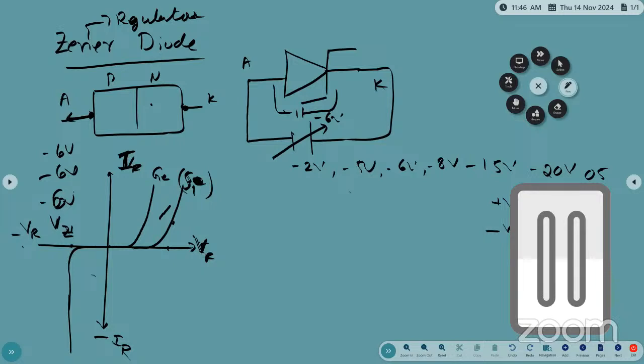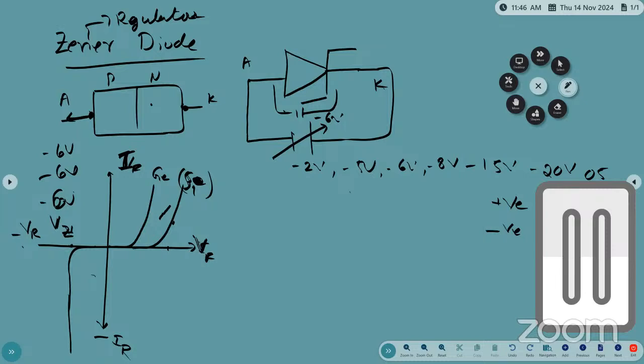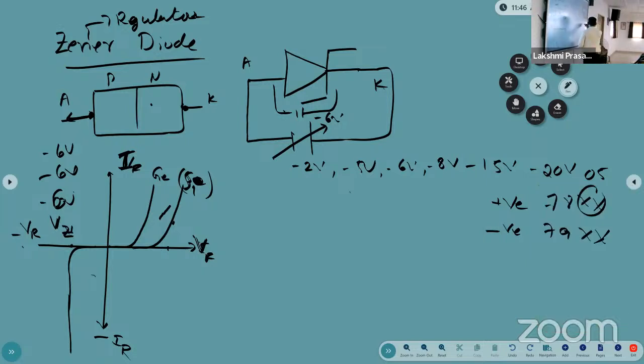If you want the output to be only 5 volt, then you can use the 78XX series. The 7805 integrated circuit will give 5 volts output supply by taking 10 or 15 or 20, any voltage, and gives only 5 volts constant. So this type of ICs are called voltage regulators. So irrespective of these two regulators, you can use the Zener also as a regulator. Note down.